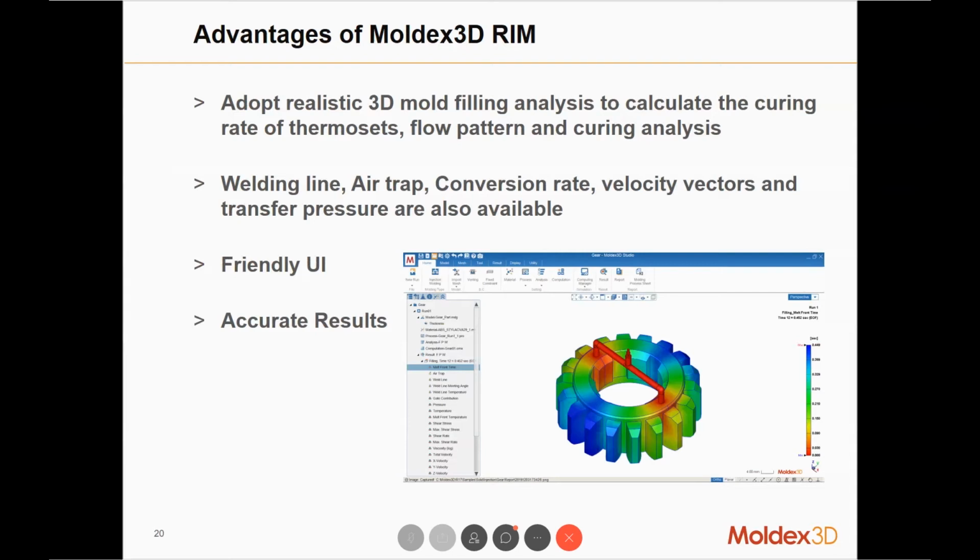And during the curing stage, we can predict the conversion rate, so users can determine a proper curing time. And based on that, we'll calculate the injection pressure, and if we're using transfer molding, then the transfer pressure can also be predicted. So a lot of information can be provided by our simulation.